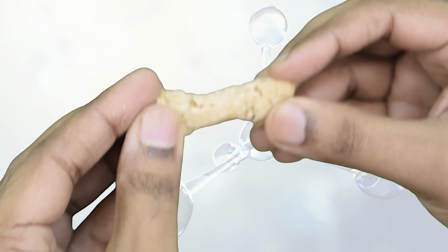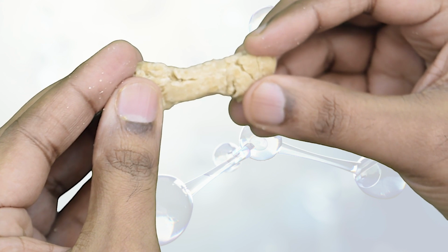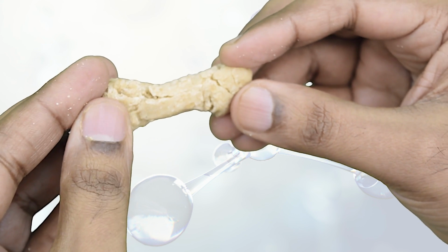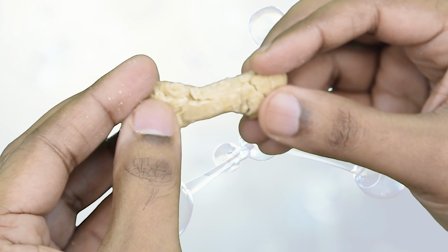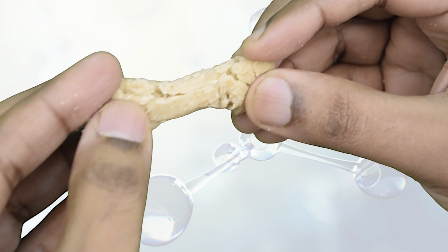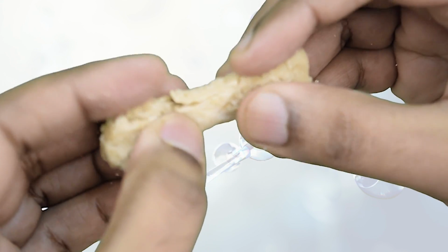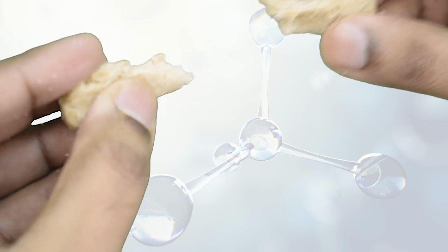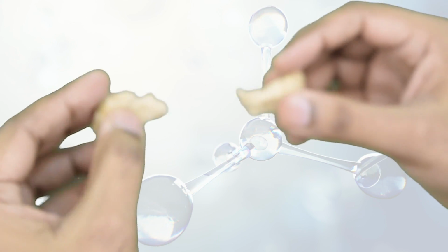I am pulling this and the stress is being acted upon this material, and you can see the diameter in the middle portion is lesser, whereas at the end portions the diameter is more, like in our tensile specimen which is placed between the machine grips. Similar to that, now I am pulling, and after pulling, this necking will take place, and finally fracture. So this is the process for the steel specimen also, which is there in the machine.